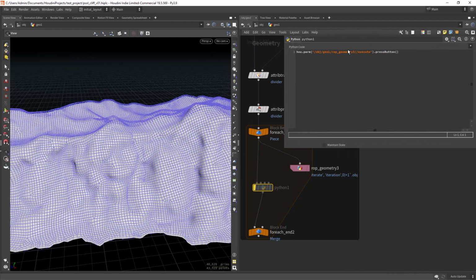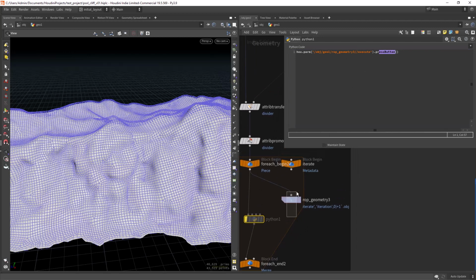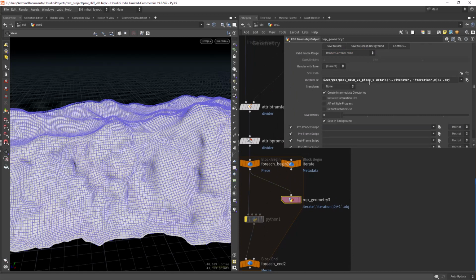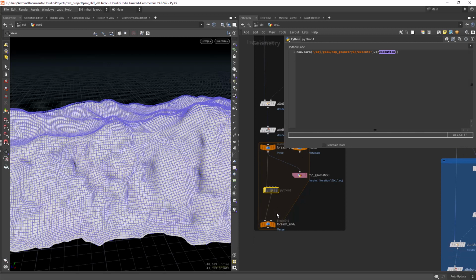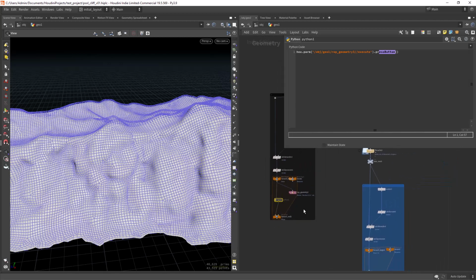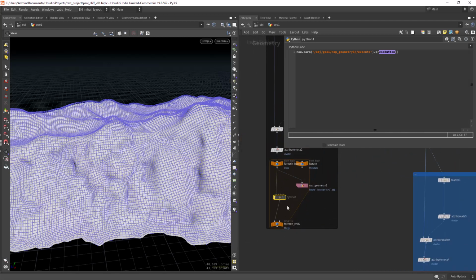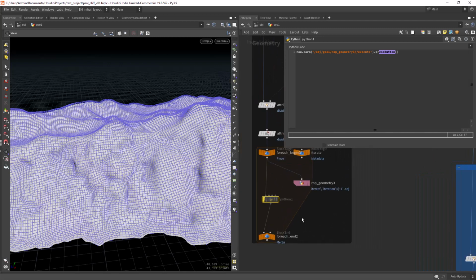So I'm just executing the wrap geometry by using the press button function, and in the wrap geometry I'm using the iteration detail attribute to name the pieces. And yeah, the Python here does everything. Then you execute the loop and check this node, render these nodes, and it will automatically export each part to a file.